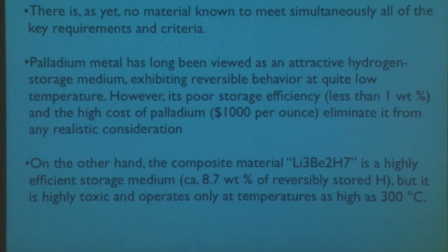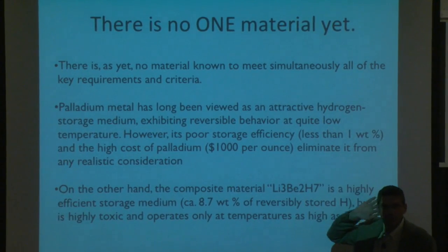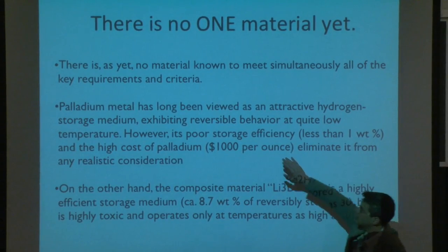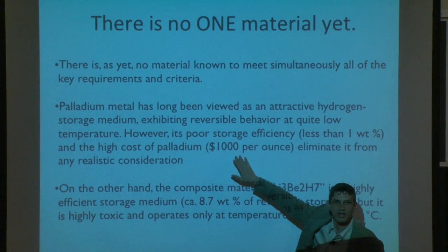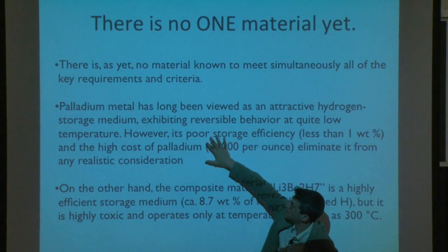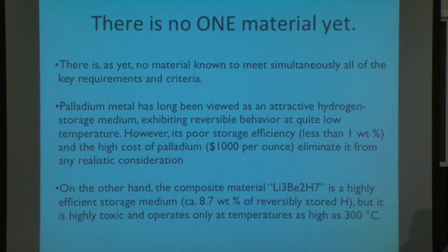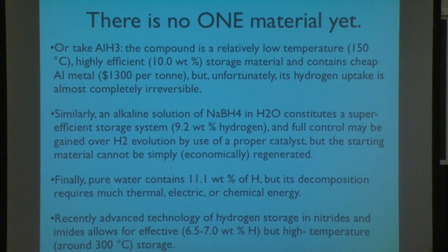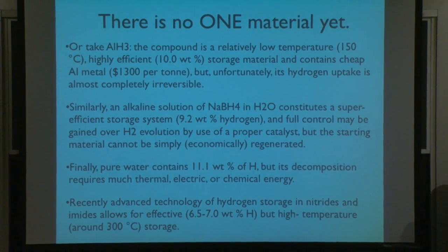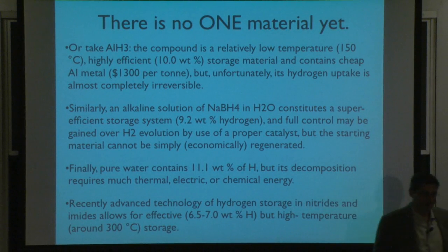And so I'm going to finally come to, now I have a few slides here that I won't go through, but they're just here for you to look at, just looking at a few cases of different materials that have gotten a lot of attention in the last 10 years. And what I do is I tell you why they're interesting and what their challenges are. Okay, so we go through a few. There's aluminum hydride. You go from the pure aluminum to aluminum hydride, back and forth. You can get up to 10% weight, but it's almost completely irreversible, right?